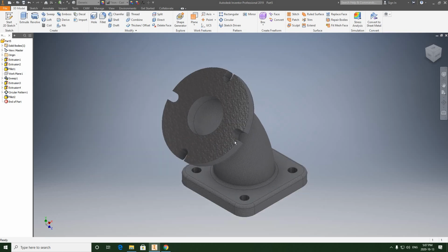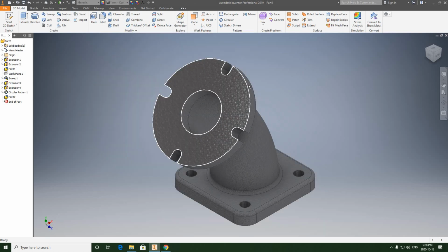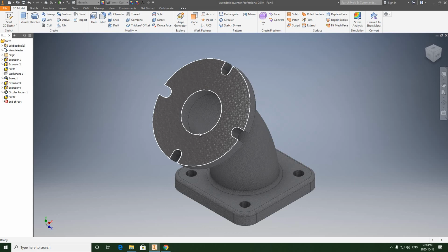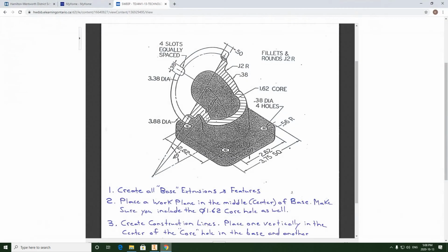Quite a few steps, but again, this is an advanced level modeling procedure, right? Being able to interpret the drawing, creating the sweep. Okay, so we did establish earlier that this center line travels on the bottom of the base, comes from a center point origin for a radius of 4.88, and it looks like the center line travels and hits right in line with the top surface of that face that's machined on top of those slots. Of course, this is only cut to show you the inside of this.